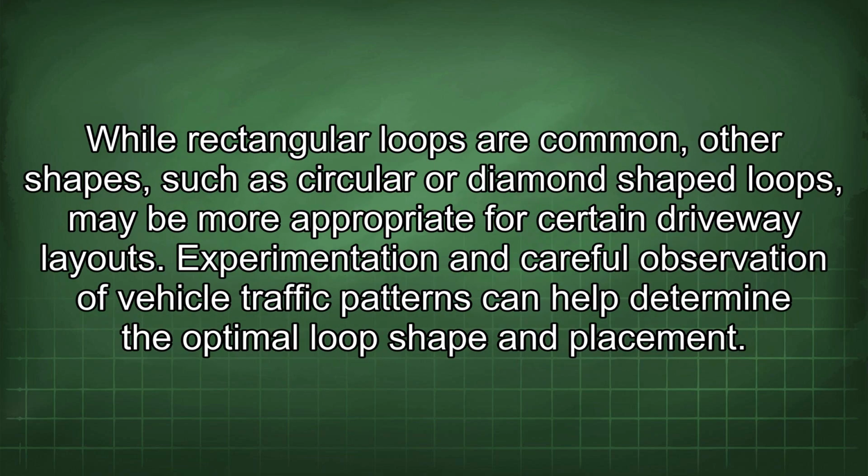While rectangular loops are common, other shapes, such as circular or diamond-shaped loops, may be more appropriate for certain driveway layouts. Experimentation and careful observation of vehicle traffic patterns can help determine the optimal loop shape and placement.